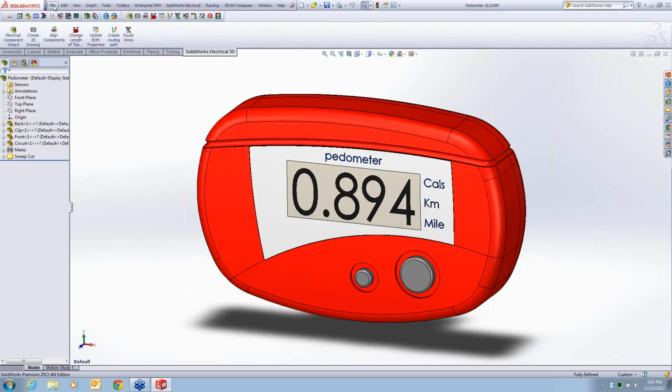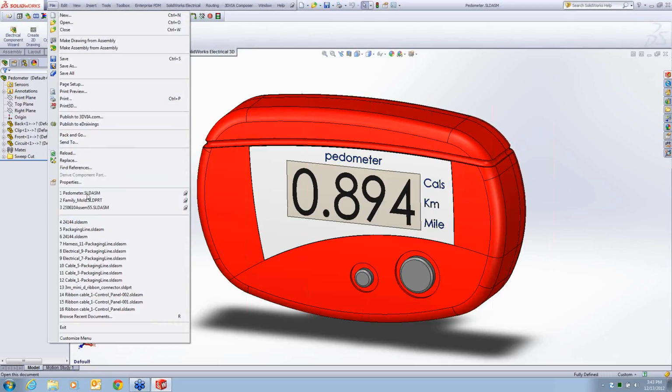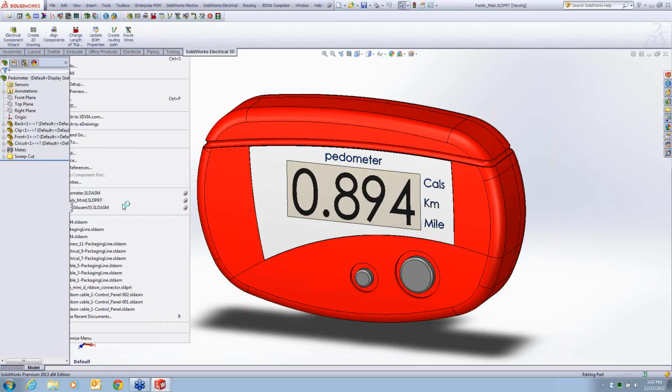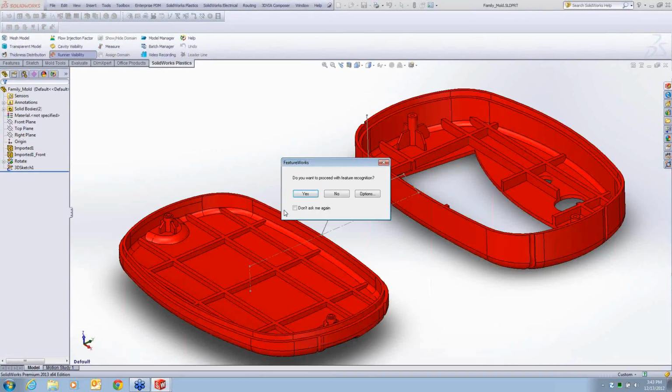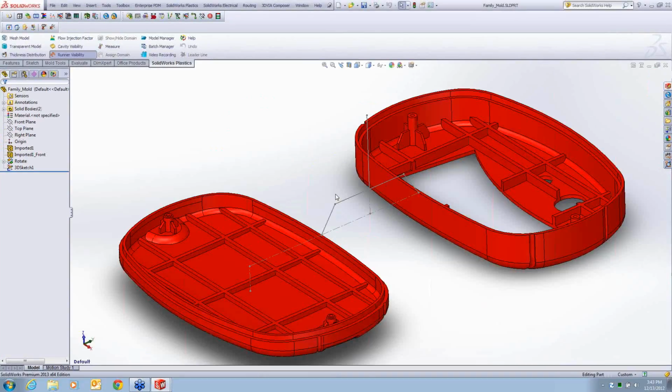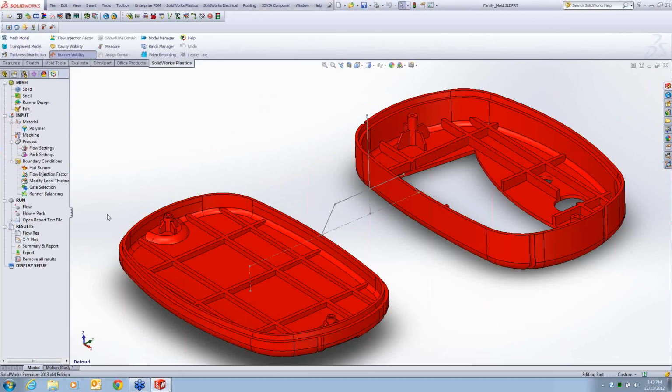When you're doing something like that, especially if these parts are going to be mating and become one overall assembly, generally what you're going to want to do is have these things be made out of the same mold. The reason is that you want it done out of the same mold process, so you have the same structural materials, the same color distribution, things along those lines.